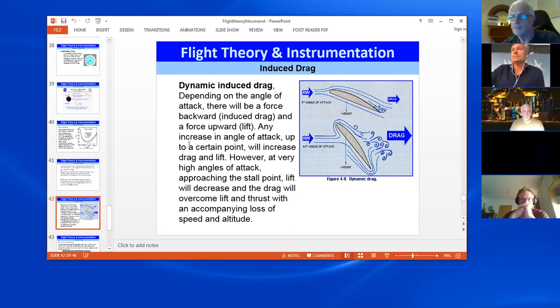What stalls it? Now, if I open this up to questions, most people say, well, you stall a wing by applying brakes or slowing it down. So my question is, why does that stall a wing? What is it about putting on the brakes that causes a wing to stall? Now, you stall wings when you land: you brake hard, you collapse the back, the wing drops.